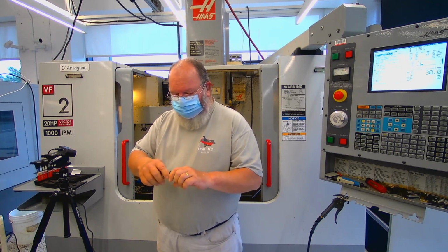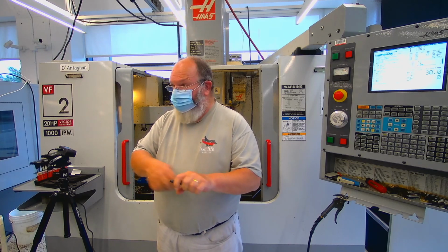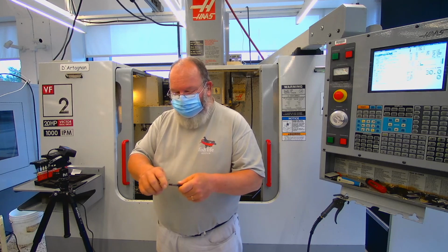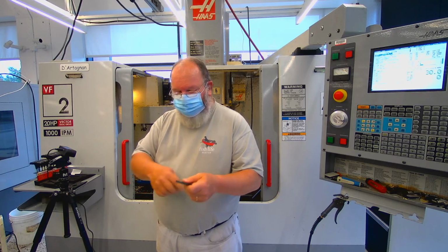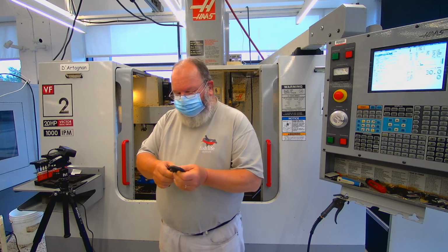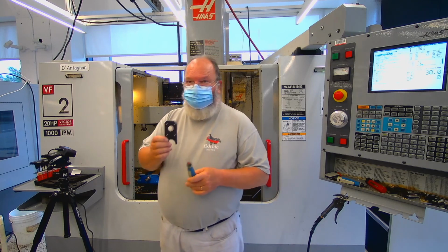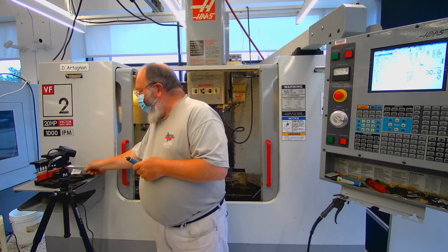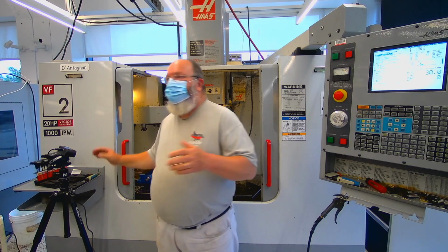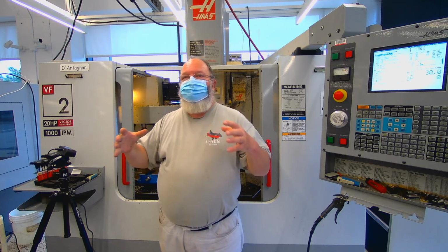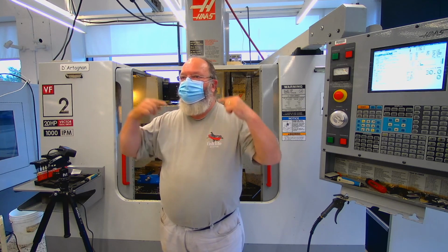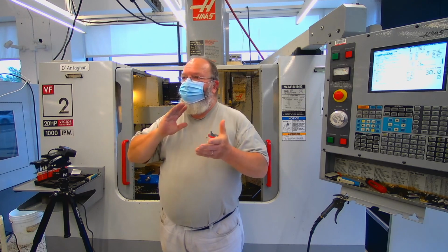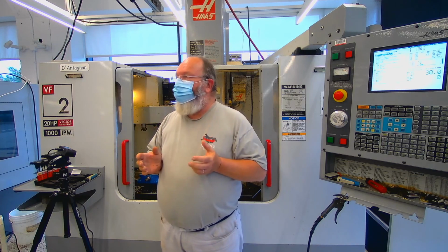We do it in any kind of quantities. We're certainly not going to do it this way. The other manual deburring tools are files, there's abrasives. Normally I would throw this to the one who looked like he took the worst nap in my demo. If we were doing this in quantity, we might put it in a large drum with some small stones and soap and water and keep rolling it and let the stones crash into the edge and round them over.